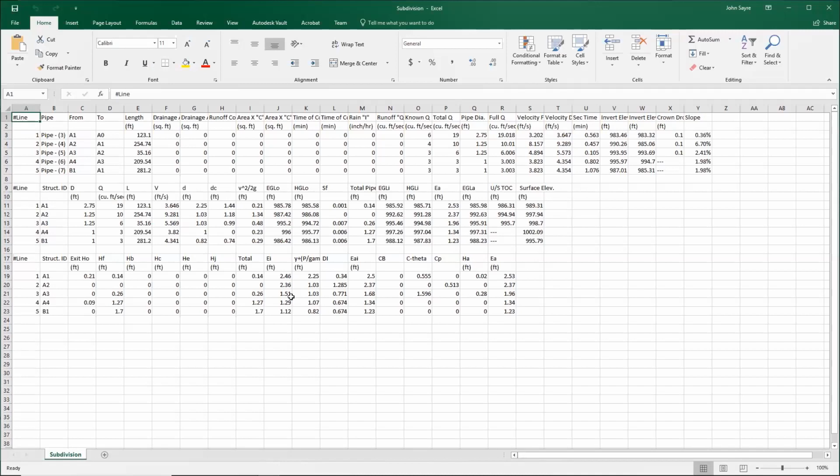So these are some of the results or reports that were missing in the previous release. But with the new release, you can understand this better. Things like the hydraulic gradient line, the overall energy within that particular pipe, so that's the V squared over 2G. I won't go into details on that, but these are some of the things which I'm very sure you are likely to be interested in seeing. So instead of still looking for some other third-party products to integrate within Civil 3D, you are now able to perform analysis of a gravity pipe, so that you'll be able to generate this kind of results.